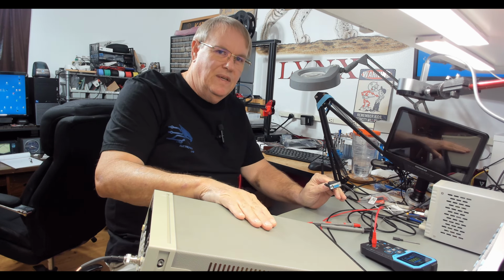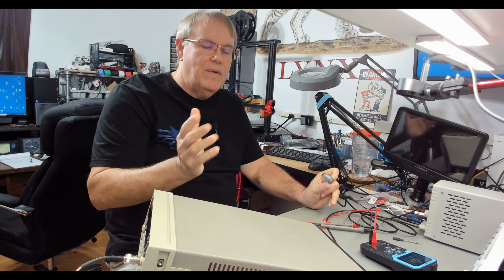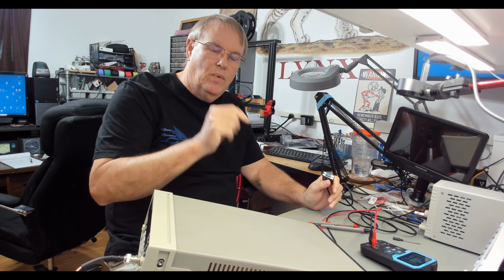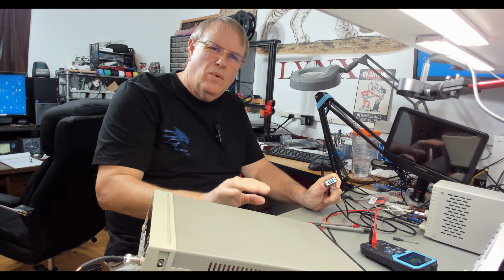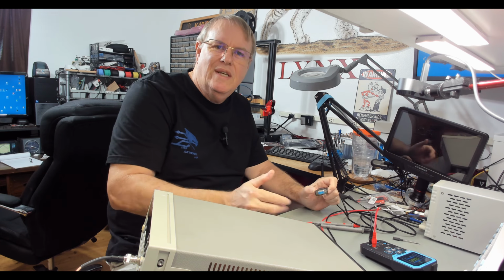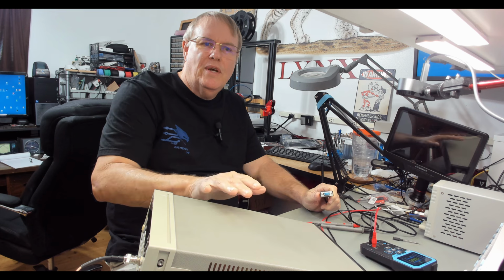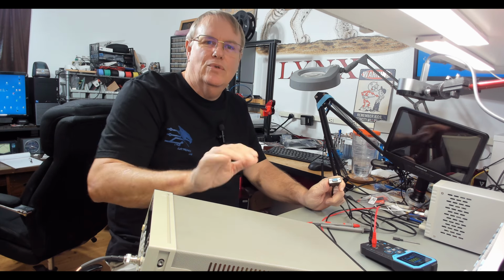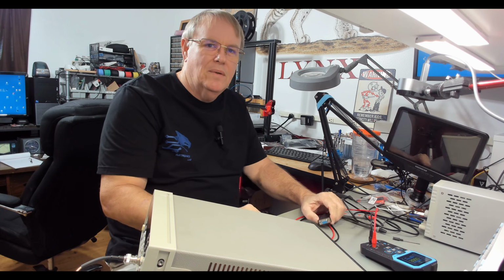If this is a DCE and this is a DTE, you would not use a null cable. So even though everything I saw online said use a null cable with this, I'm thinking that's because they were thinking of hooking a printer to it, which was the original intent of that port. But I found stuff talking about hooking to a computer. Here's how you do it, here's the settings you need, and you use a null cable. This is telling me that should not be the case.